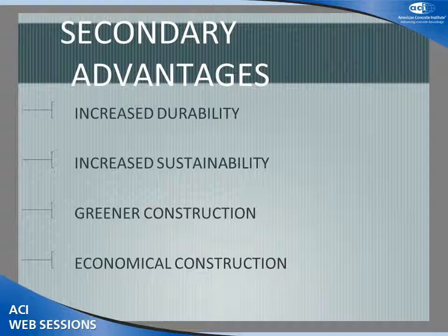Type K cement is an interground product manufactured by combining two clinkers before the grinding process: the mill's standard cement clinker and a Type K clinker. The exact proportions of each clinker vary from mill to mill, and minor variations from batch to batch are sometimes experienced at each mill. Why such variations, you might ask?